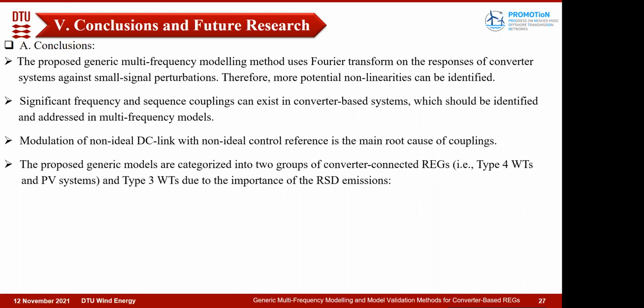And also the proposed generic model, we categorized it in 2 groups. One is the converter connected REGs, meaning that type 4 wind turbines and PV systems. And the second group can be dedicated for type 3 wind turbines.